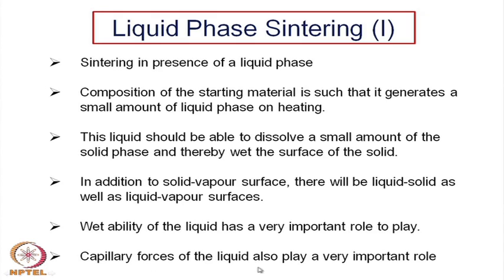Capillary forces of the liquid also play a very important role, because in between the grains we have some kind of capillary size of the pores or the openings, and that capillary force also helps in the distribution of the liquid throughout the matrix.